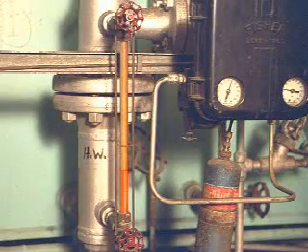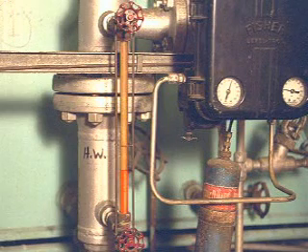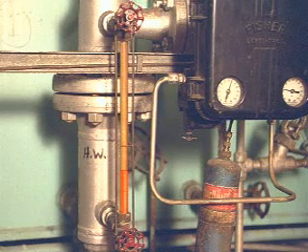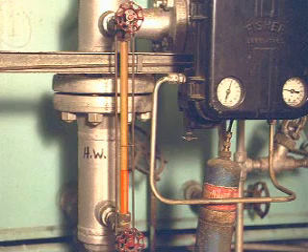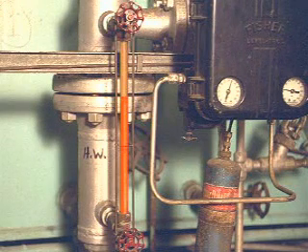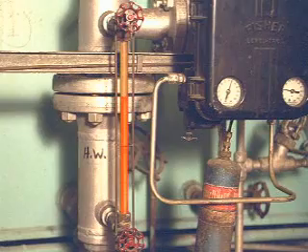A low hot well level occurs when the amount of condensate leaving the main condenser is greater than the amount of steam that's condensing. This condition could cause the condensate pumps to lose their prime. A high hot well level occurs when the amount of steam condensed in the main condenser is greater than the amount of condensate removed by the condensate pumps.